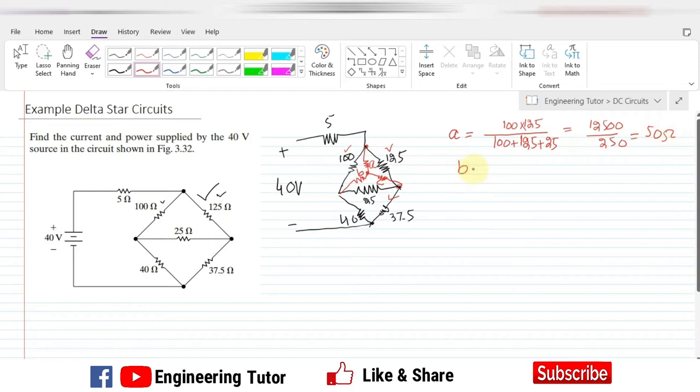Similarly for B, the denominator remains the same by adding all three resistors, which is again 250. For B, the two resistors connected with this junction are 25 and 100. So 25 multiplied by 100 divided by 250, simplifying, we get 10 ohm.